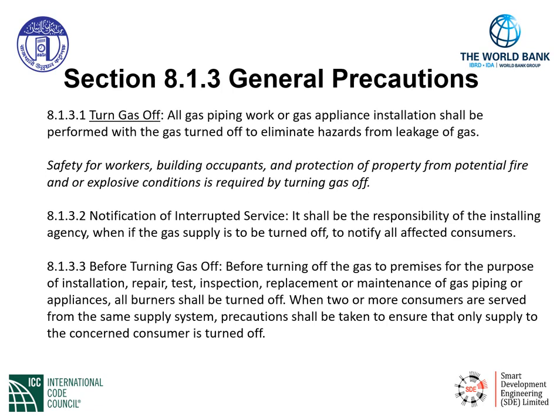Section 8.1.3.3 is titled Before Turning Gas Off. So before we turn the gas off, we need to verify some things. Before turning off the gas to premises for the purposes of either installing, repairing, testing, inspection, or even replacement or maintenance of the gas piping system or appliances, all burners shall be turned off.